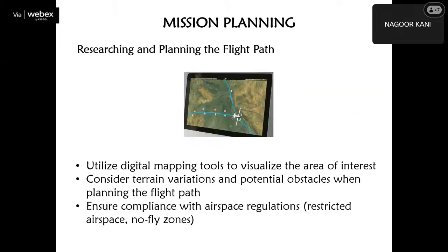In survey mode, if you give the area, most of the software automatically plans the speed and flying height. If you give the resolution, which GSD you want to capture your data at, it will provide all the details. So accordingly we can plan. They are not very complicated currently, due to technology advancement.